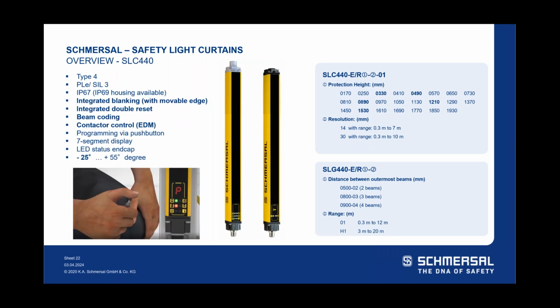The next, we would move to what I would consider our catch-all, and the bulk of our applications we see. This is what we would use: the SLC and SLG 440s. Again, you can read all the same type 4 PLE, but now we're able to program blanking, the double reset, beam coding, external device monitoring, all that can be done. You can see in the picture in the bottom left, he has the programming cable, which we sell separately, but it's so simple. You attach that to the light curtains and you literally toggle through. It's a single push button toggle switch. You toggle through all the programs, hold it down for 3 seconds to activate whatever ones you need. So again, super easy to program, and multiple programs can run at once.